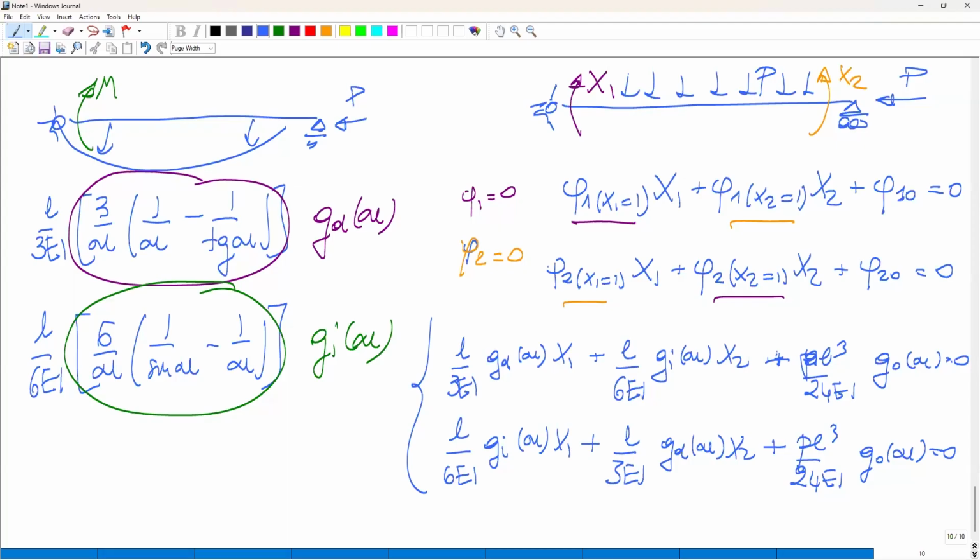And so which is the condition for which that system of equations can admit infinite solutions? Well, it's exactly the opposite of what we said before. If the condition for having one and only one solution is that the determinant must be non-zero, if that determinant is zero, you will have infinite solutions. And the determinant of the coefficients going to zero is the condition for the buckling failure.